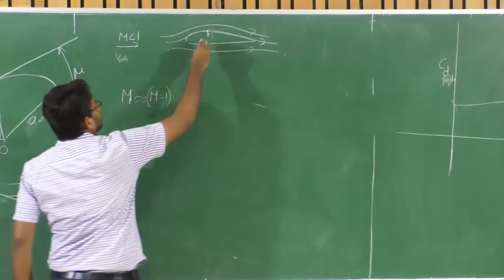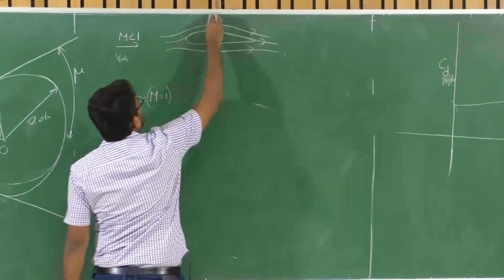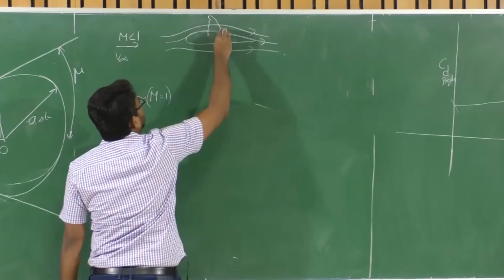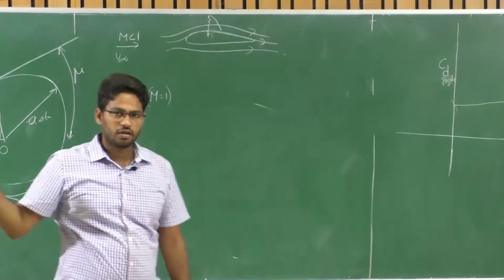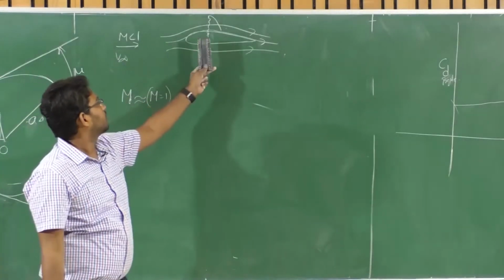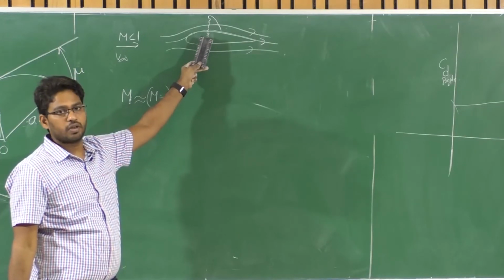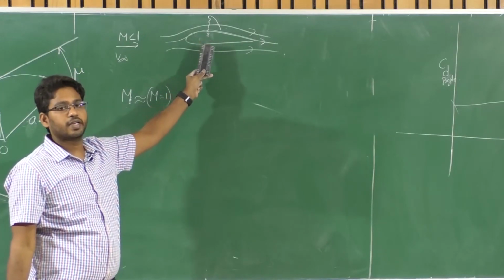The local flow accelerates and you will see a shock wave on the surface of this wing, right? So the local subsonic speed at which the airfoil or the aircraft first encounters a Mach wave or sonic speed is known as the critical Mach number.